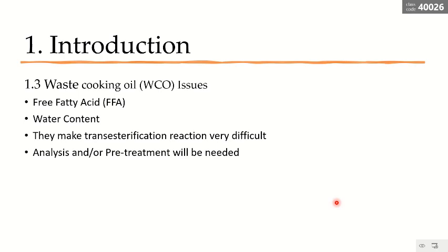So the free fatty acid and water content will make the following step, which is called the esterification reaction, very difficult. So analysis and pre-treatment of this waste cooking oil will be needed. Actually, it will be a must if we want to carry out this production.